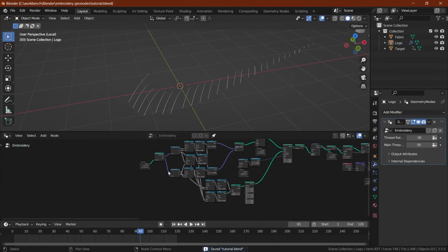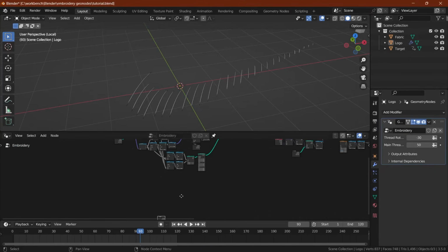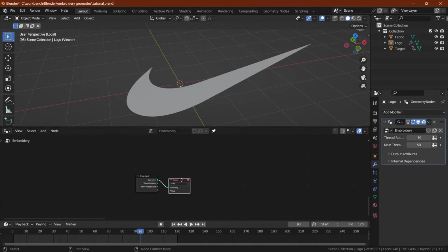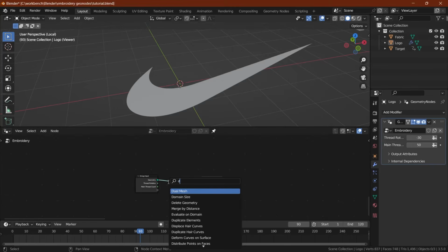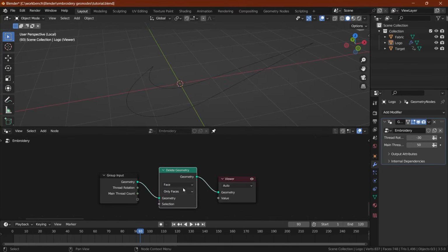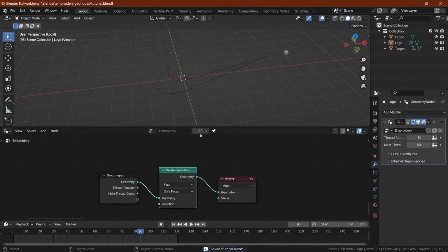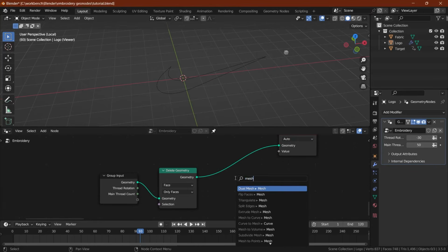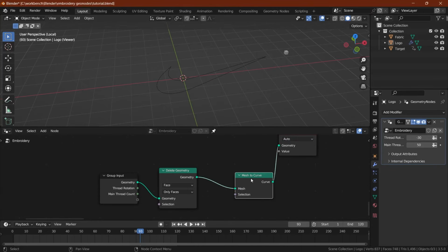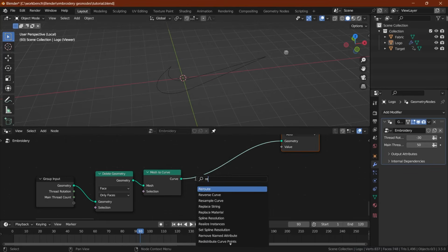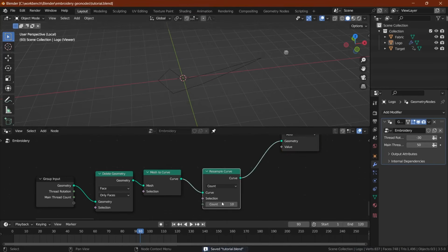The last and quickest process is to add the border embroidery. The steps are similar, but not exactly the same. Let's take the original geometry and delete only the face so we're left with just the edges. We'll convert this into a curve. To add a specific number of points on it, we'll resample it.